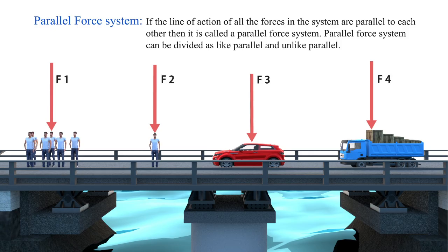Like parallel because the direction of all the forces is the same, and coplanar because the line of action of all forces is in the same plane. If we consider the support reactions generated at the contact between the bridge and the beams that support the beam, then the complete system is known as an unlike parallel coplanar force system.